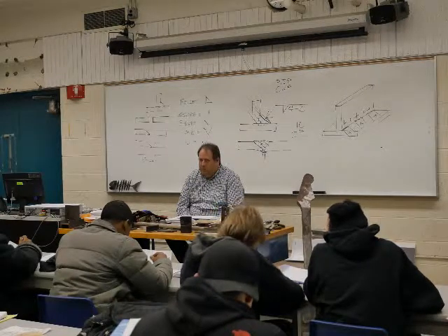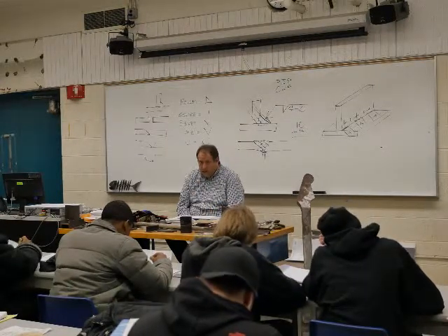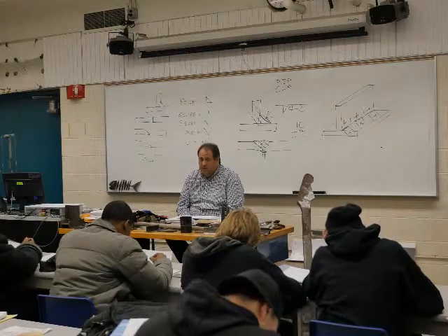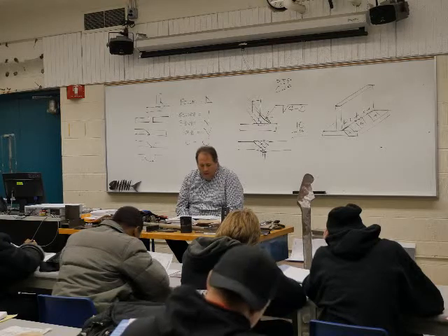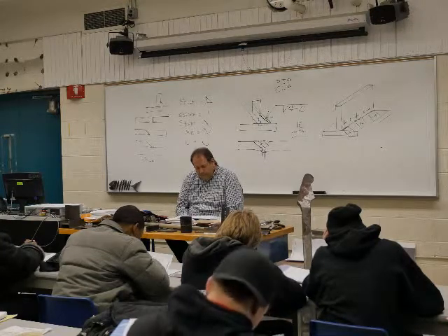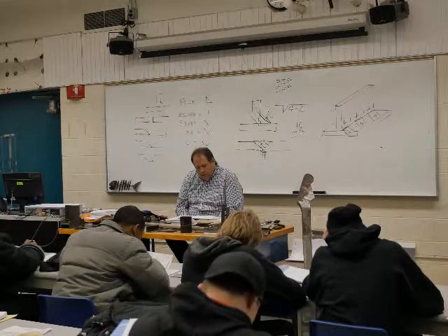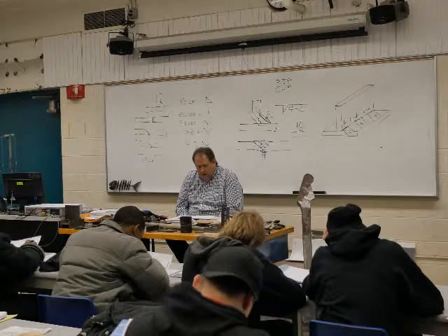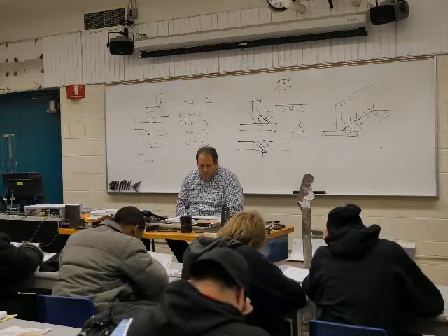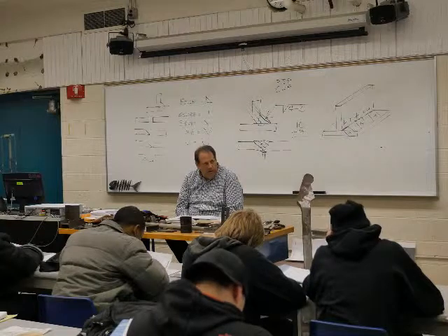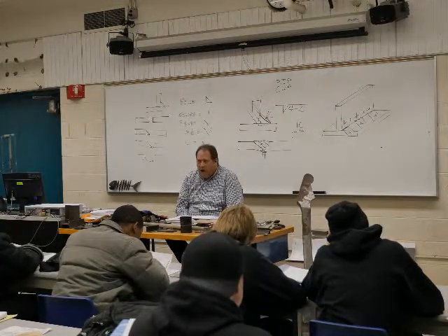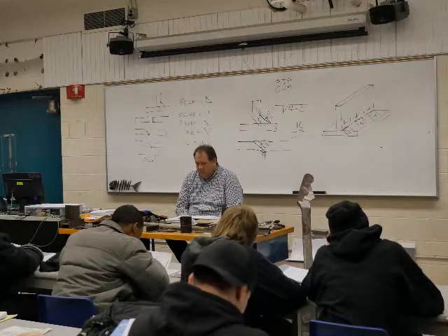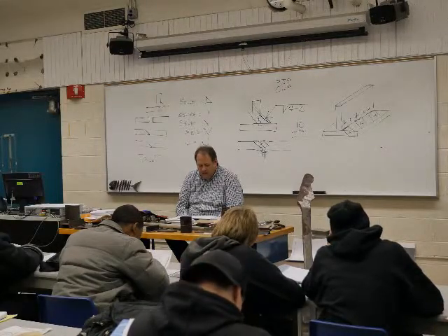It's probably something specific to this print, probably on a note somewhere, so I'm not going to worry about that at this point. And then we have a 1/8 fillet weld, contour symbol of flush, flat, but in 2 different spots. Both sides.